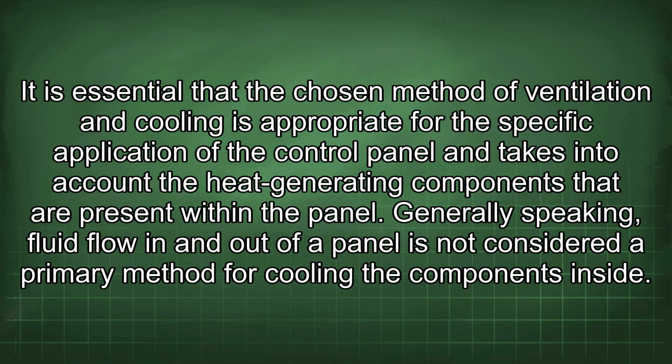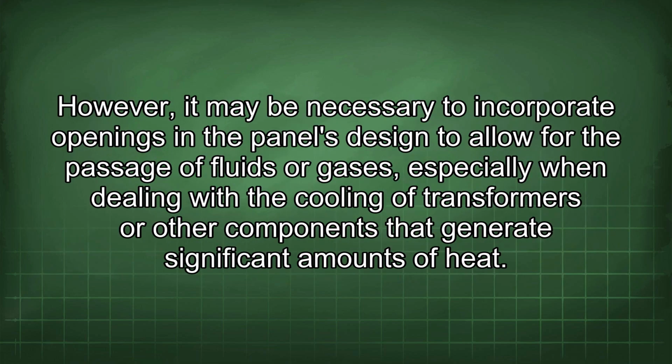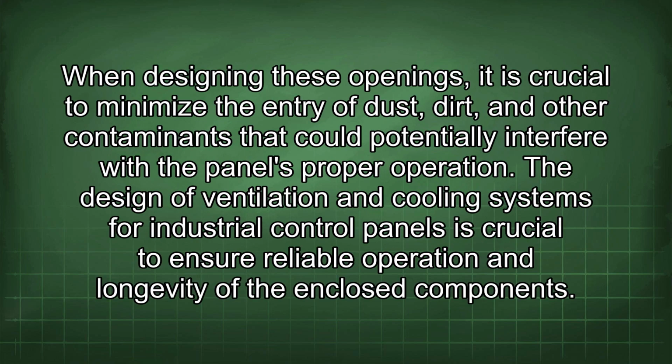Generally speaking, fluid flow in and out of a panel is not considered a primary method for cooling the components inside. However, it may be necessary to incorporate openings in the panels designed to allow for the passage of fluids or gases, especially when dealing with the cooling of transformers or other components that generate significant amounts of heat. When designing these openings, it is crucial to minimize the entry of dust, dirt, and other contaminants that could potentially interfere with the panel's proper operation.